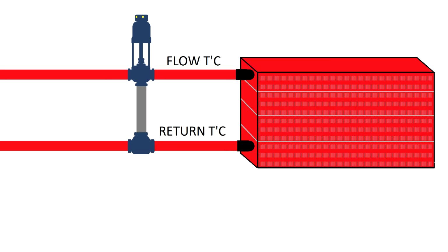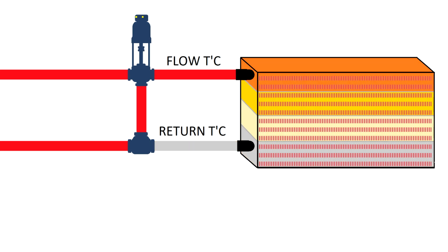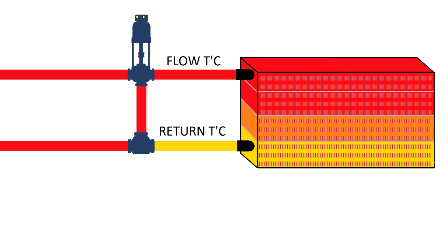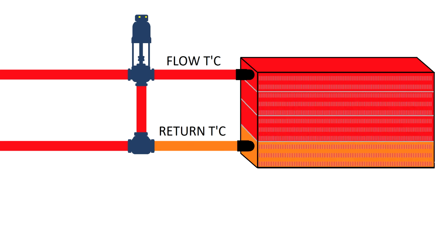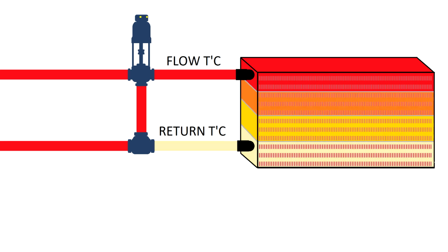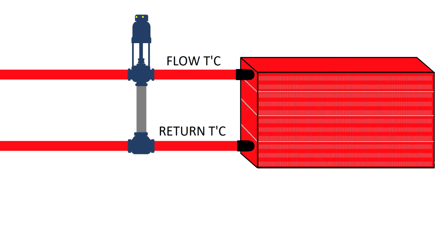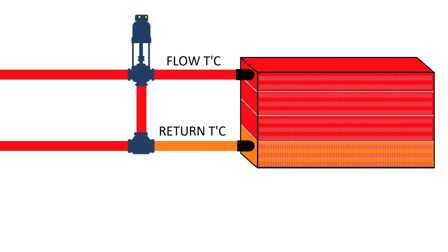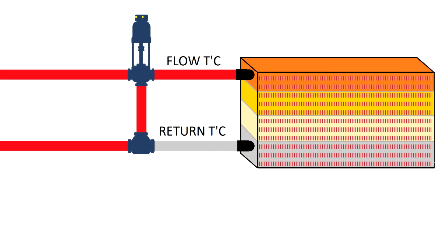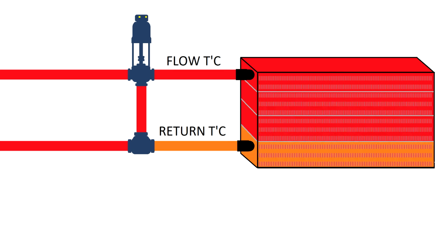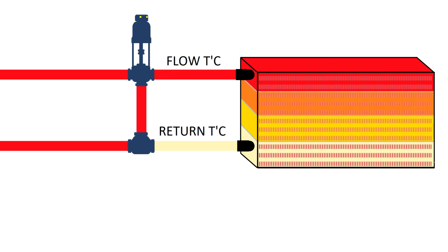And if you have a problem with your heating agent, then you'll sometimes be confused if you don't know what temperature you're supposed to have on this heating agent. So just be very careful. Don't always blame the three-way valve or actuator or the PLC. Don't push your fault in that direction. Just try to check what I just told you, and then you'll be successful.